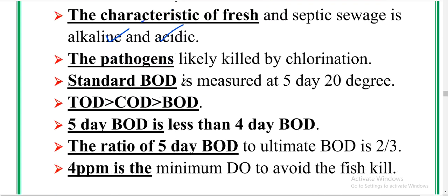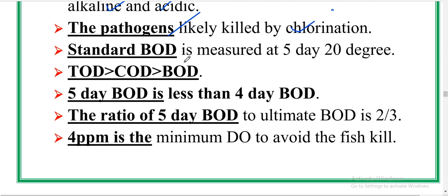The pathogens are likely killed by chlorination. Standard BOD is measured in 5 days at 20 degrees centigrade, remember. TOD is the greatest, then COD, and BOD is the least: BOD, then COD, then TOD. 5 day BOD is less than 4 day BOD, remember.